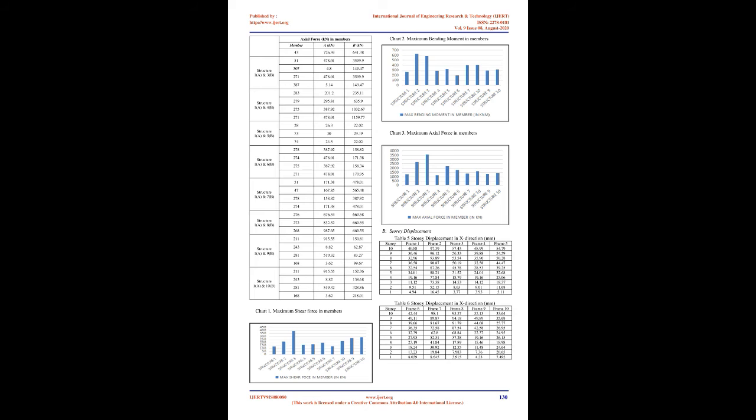Frame 5. The frame carries heavier loading on the top story, e.g. in the top story a swimming pool has been introduced, hence making the top story heavy, and the building becomes irregular. Frame 6. In this frame the intermediate columns are removed, making the ground story soft, and thus an irregularity is introduced in the building. Frame 7. The frame is made irregular by removing the end columns and placing the intermediate columns in it. Frame 8. This frame has fourth and fifth stories soft. No floor beams, horizontal, have been provided, which makes these 2 stories soft.